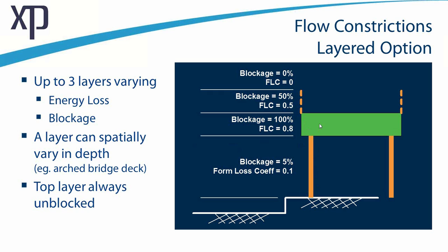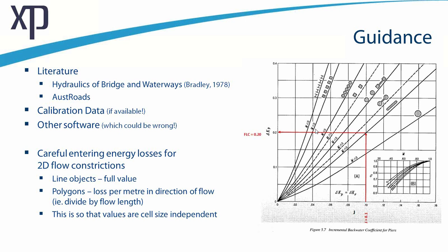Another good practice is to compare with other software such as HEC-RAS, but you do have to be very conscious that it is just another model, another approximation, and if it is a very tricky or complex structure, the more ways that you look at estimating the afflux and losses and checking your model, the better. It's just very important to note that these structures are effectively a complex 3D problem, and we're trying to simplify it down to a 1D or 2D solution.